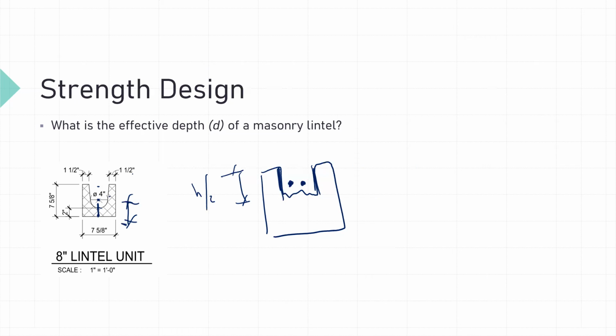And we can orient those either this way, right side up, or we can orient them upside down, which is done on occasion. So they'll knock out that crossweb again in our units. We'll put those longitudinal bars in here. And we could then use either like chairs to support these longitudinal bars. And we'd have some type of plywood or OSB down here so that when we grout this solid, we are keeping the grout confined to our lintel. So we could do that with chairs.